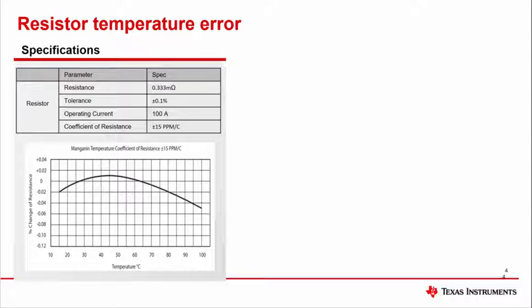In a current sense application, a shunt resistor can be treated as a piece of equipment. When working with high-precision current sense amplifiers, the error of a shunt resistor becomes important. An interesting property of resistors is their change in resistance versus temperature. When passing substantial current in a shunt resistor, the resistor will dissipate that power, causing it to heat up. Once the temperature changes, the resistance will change, causing a gain error in current measurement.